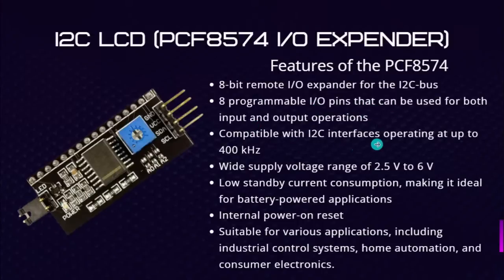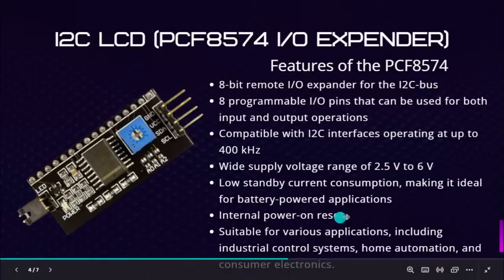Compatible with I2C interface operating at up to 400 kHz. Wide supply voltage range from 2.5 volt to 6 volt. Low standby current consumption, making it ideal for battery powered applications. Internal power on reset, suitable for various applications including industrial control systems, home automation and consumer electronics.